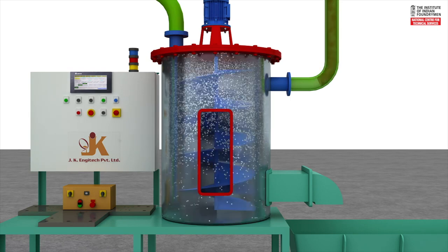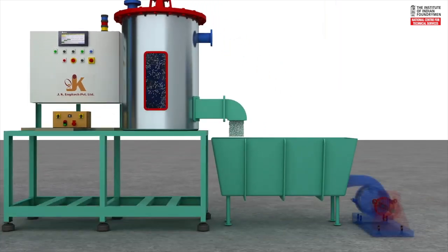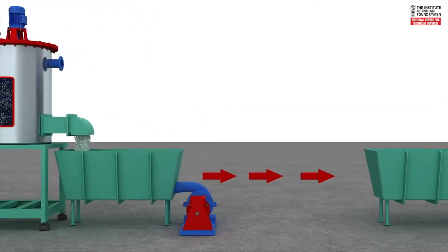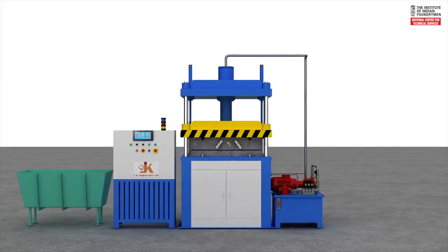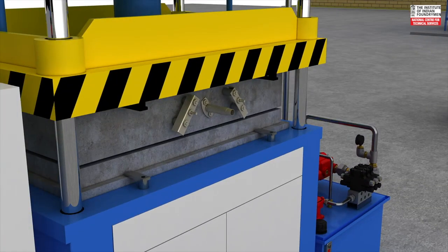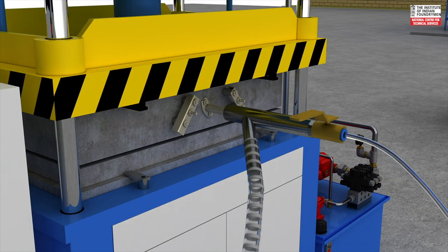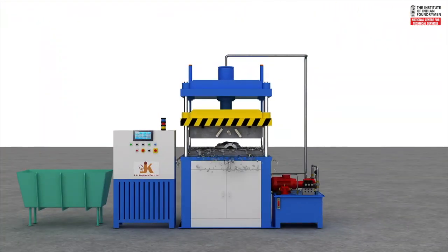But I found one lacuna, or one incorrect thing, in this video: the refractory coating is shown applied to the individual component. It has to be applied after tree assembly. That is, this total assembly has to be coated. Herein they have shown that the coated component is placed on the coated tree. But actually coating happens to the full assembly.